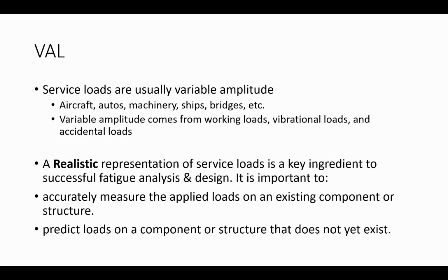This variability comes from the working loads themselves, changes in vibrational loads, as well as accidental loading. It's important whenever we're designing to resist fatigue that we apply realistic representations of service loads in our experiments as well as in our equations.